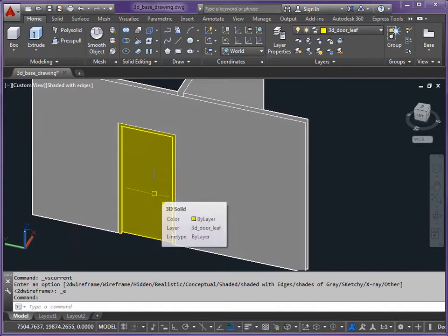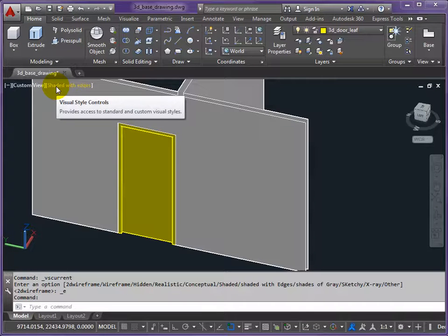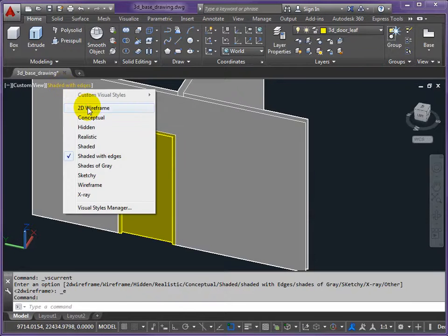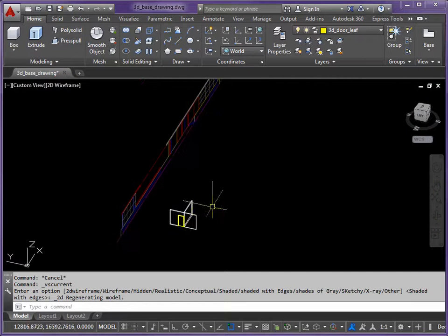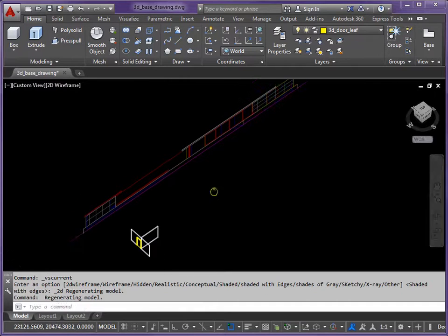But depending on the amount of time you've got and the level of detail you need, you know, you could work much more on that door and put in vision panels, door handles, kick plates, whatever's needed for the door. Now, if this was a door that was going to be used in different widths, then I might have done that as a 3D faced object instead of a solid. Then I could pull and push that to suit different door openings. Okay, so that is the final part of the model.